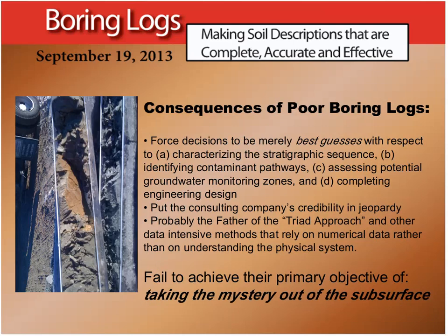What's the price of poor boring logs? Well, it forces us to make best guesses from insufficient information. Groundwater monitoring systems, excavation depths, foundation designs, and remediation approach are often based on boring logs that don't do their job. It forces us to cope with uncertainty. Boring log information often lacks geologic context to create meaningful correlations from boring to boring, and also fails to help us understand the distribution of physical properties such as hydraulic conductivity in the subsurface.